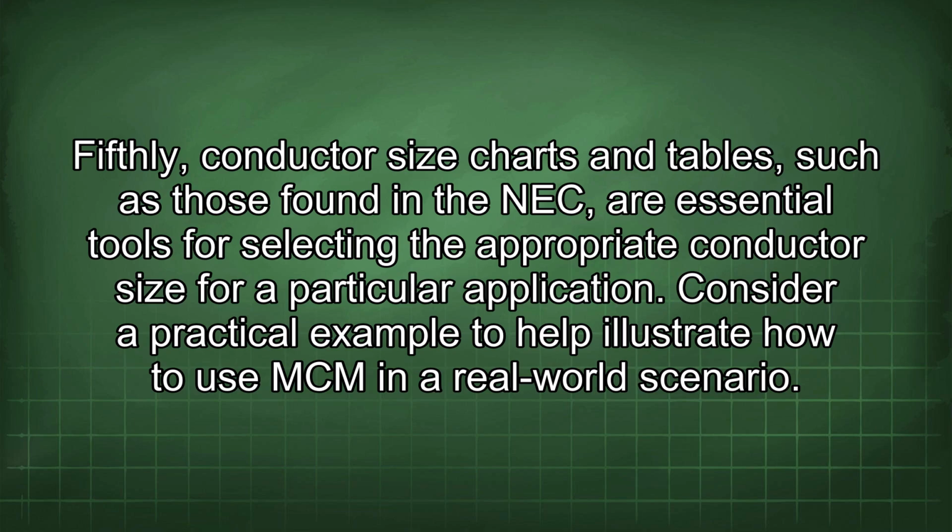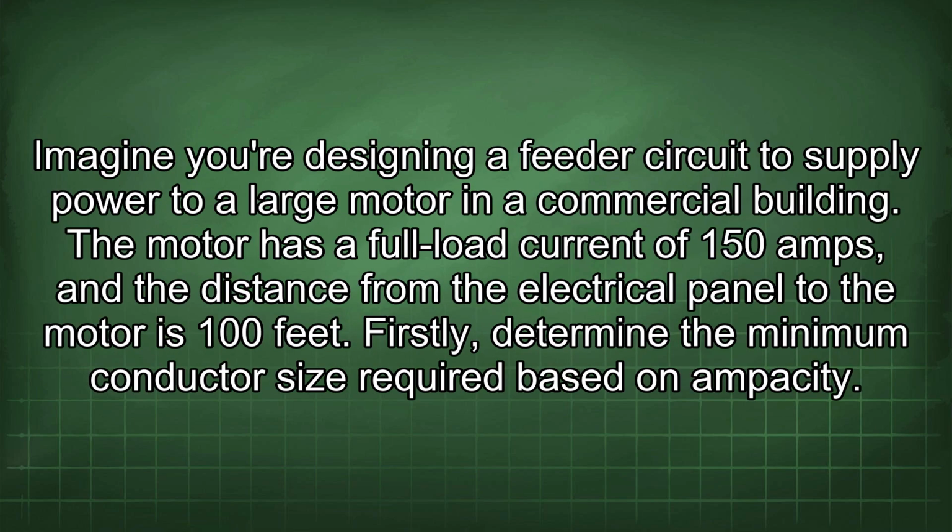Consider a practical example to help illustrate how to use MCM in a real-world scenario. Imagine you're designing a feeder circuit to supply power to a large motor in a commercial building. The motor has a full load current of 150 amps, and the distance from the electrical panel to the motor is 100 feet. Firstly, determine the minimum conductor size required based on ampacity.